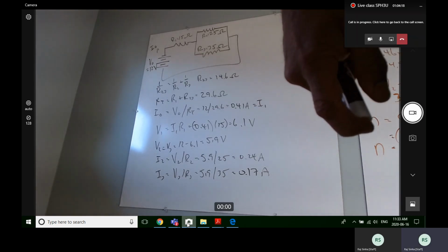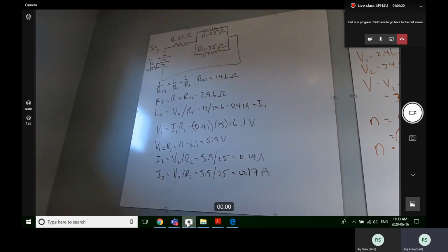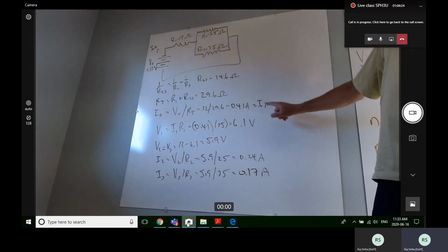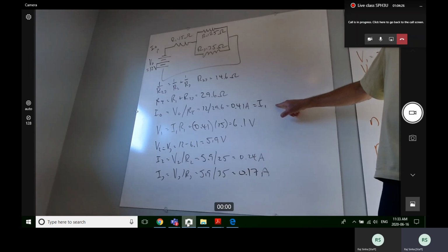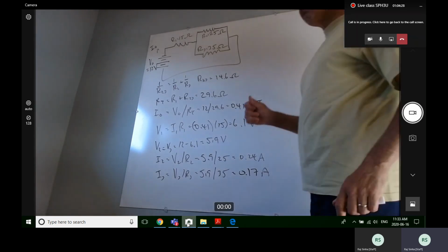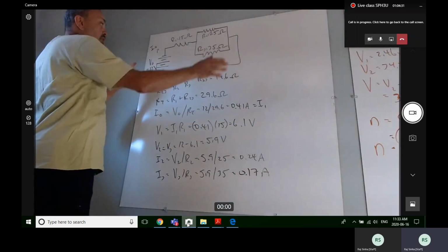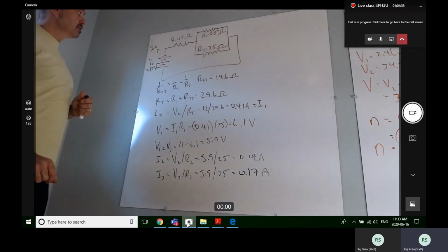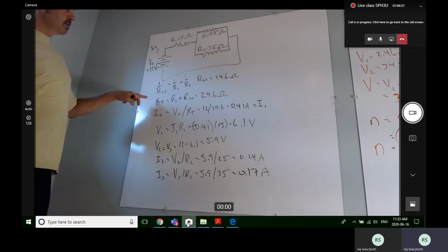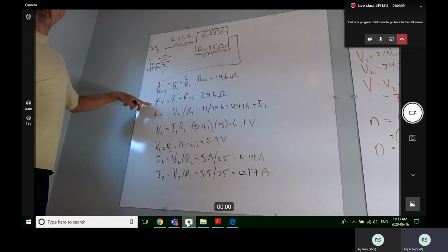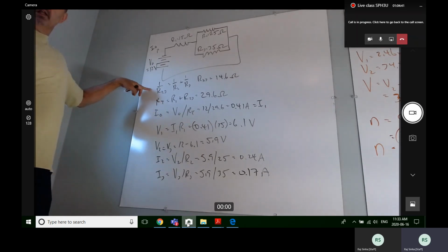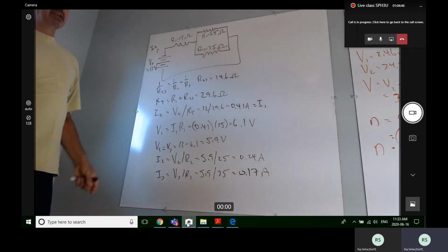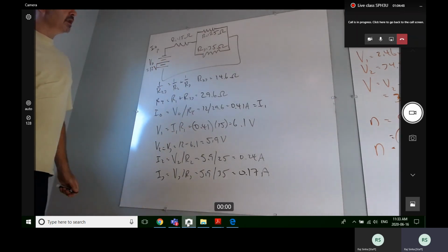you're okay with this. It really looks ugly because there's a lot of math, but it's V equals IR, V equals IR. Right, it's all Ohm's law, right? Because in the circuit, I have a V equals IR. In every resistor, I have a V equals IR. Right, so, and then I've got series things, RT equals R1 plus R2 plus R3 plus R4. I've got my parallel resistors, 1 over resistance total equals 1 over the resistances added up. Right, so there's not a lot here.